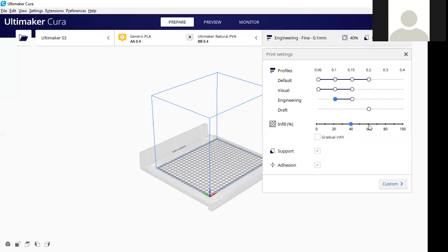Okay, so infill is just to tell you the spaces between the lattices of your build. All right, so that is what this is for. Then support is maybe if you want to create what we call an overhang, something like a bridge. You can't do a molten bridge. You have to build a support, and this is applicable to when you use a dual print core. So if you have a mono print core, this will not be applicable.